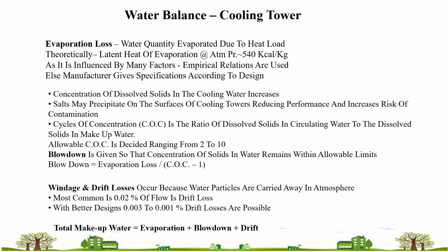So it's basically the ratio between the TDS of the circulating water and the makeup water TDS. Allowable COC ranges between 2 to 10.